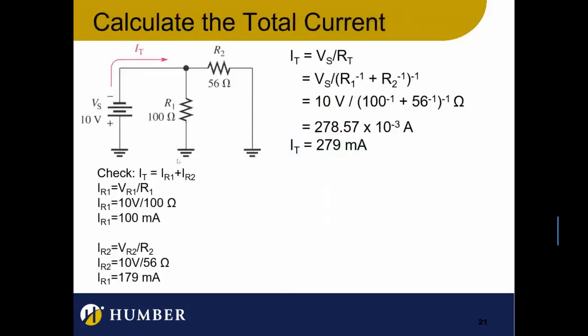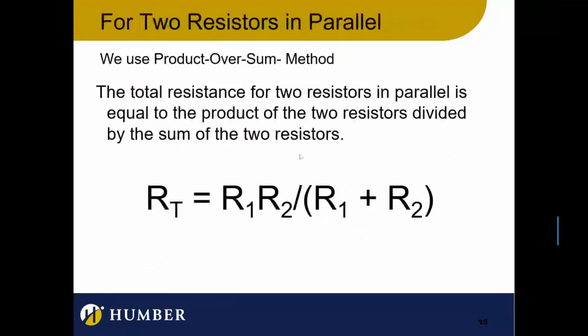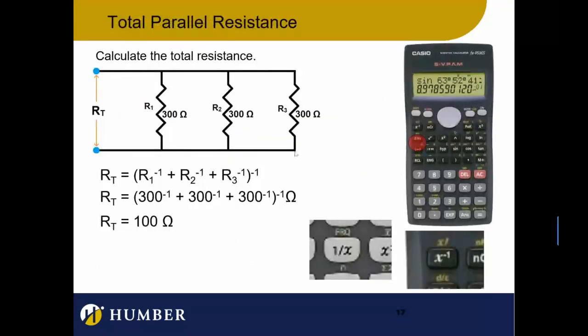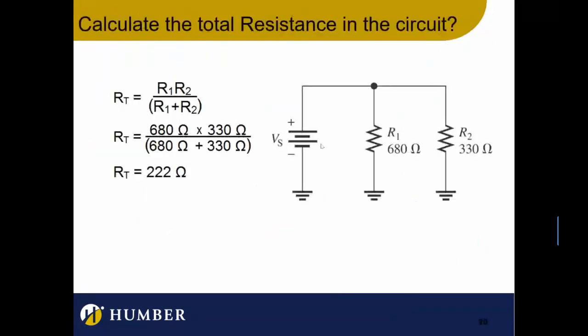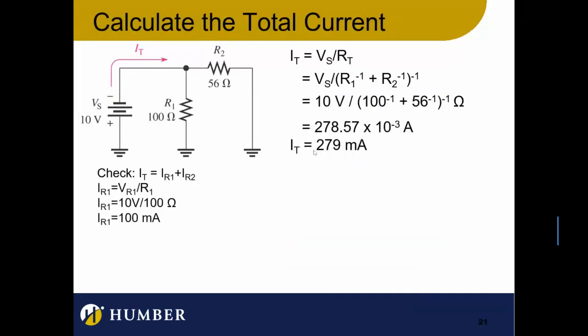For instance, that's common ground. Let me take a look at this circuit over here that I drew. This circuit has a line going all the way through, indicating that this is connected. If I just put a ground symbol here and here and here, it means that they're all connected. It saves me actually drawing a line going all the way back to the battery again,